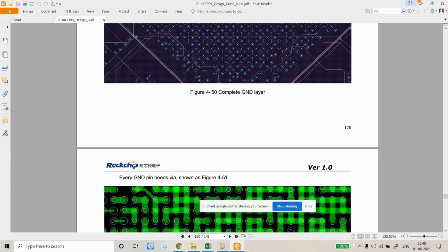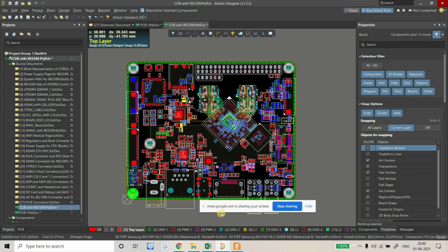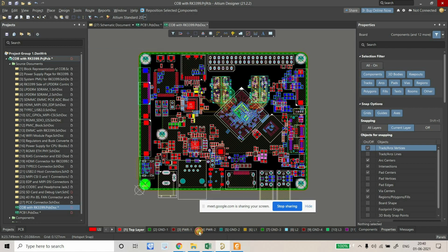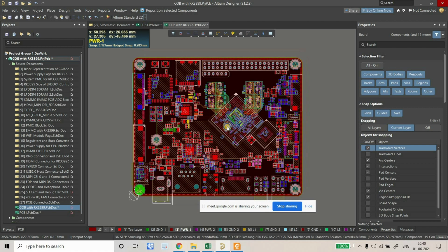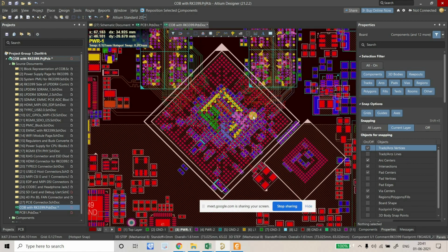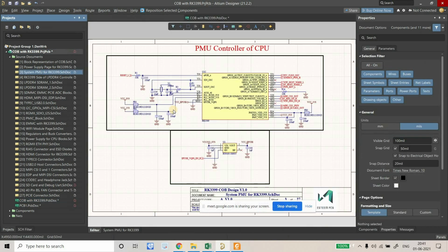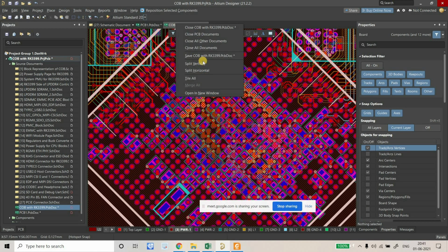Okay, let's talk about power planes. For power planes, we have two power planes. I'm just going to talk about the most complicated one, which is for the SoC: how we have to section the SoC power plane. I'm not talking about a single pad which needs some supply. I'm talking about the system supply and DDR supply. Firstly, I'm just going to split it.